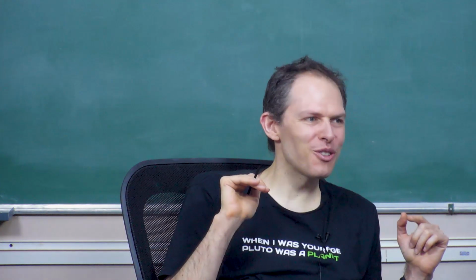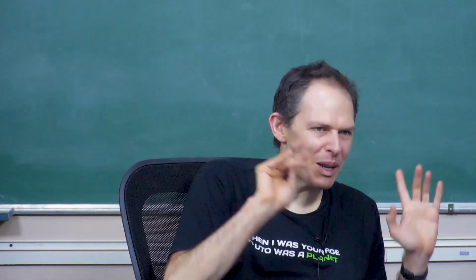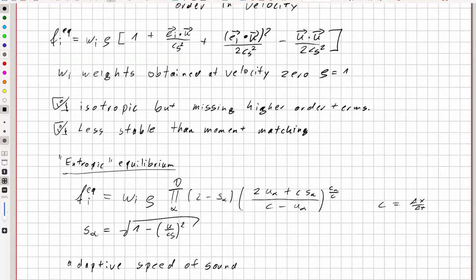I still have concerns with this because then this is, again, not isotropic, but maybe I don't see everything here. The thing why I still find this a bit ridiculous is, first of all, we don't want to run too close to the CFL condition, also because this makes it not accurate, obviously. And the second thing is we can only double the CFL condition.